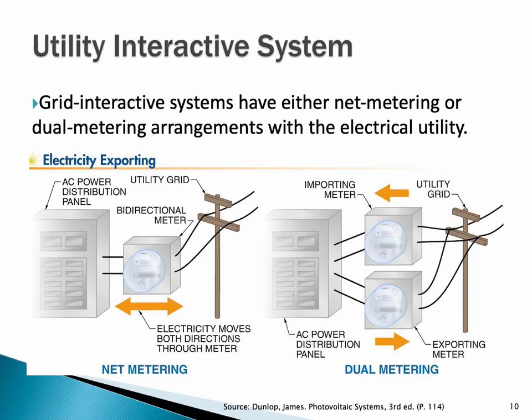So these renewable energy systems, they'll have a bidirectional meter or a double meter, a dual metering system. A bidirectional meter will clock up production and consumption, and at the end of the month you get the net reading. So either the utility owes you or you owe the utility. It doesn't tell you how much you've consumed, only how much you owe or they owe.